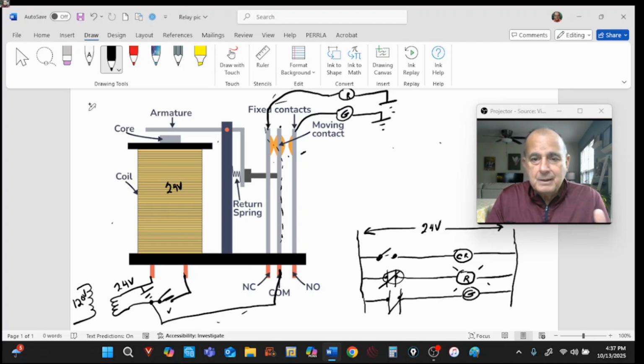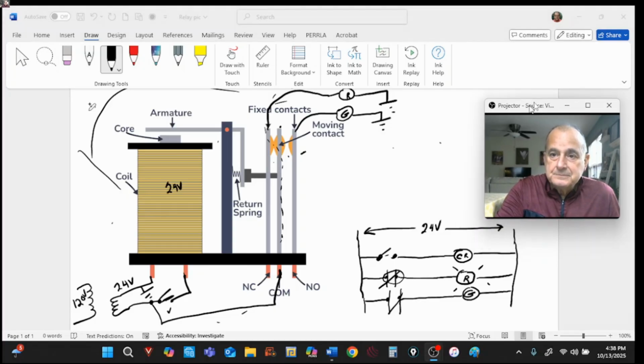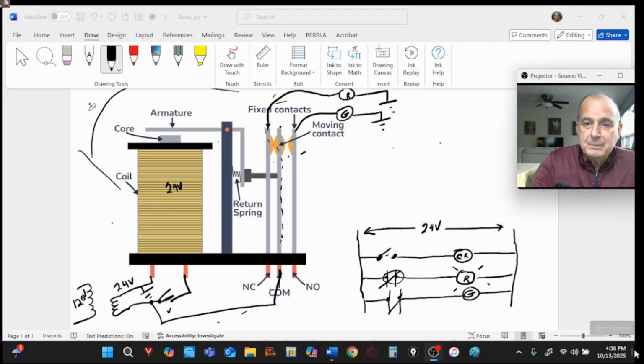It would be cumbersome to draw this whole thing in a ladder circuit like that. So we represent that with a coil like so. And you can see between the rungs, let's lift this up a second. Between the rungs, it's not drawn there, but this is actually the secondary of your transformer.